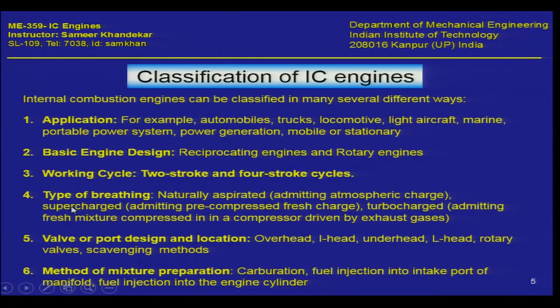However, as you can understand, if you pressurize the air, if you induct the air at slightly higher pressure, the density of that air will be larger, and because the density is larger, per unit volume you will have more oxidant, that is more oxygen available to burn. Therefore if you require larger power, that means if you want to burn more and more fuel, completely, correctly and more efficiently, then if the air is denser, you can accommodate more fuel per unit volume of the cylinder.